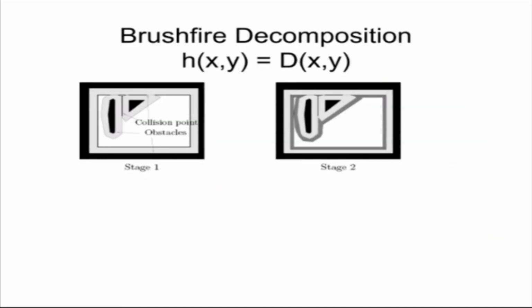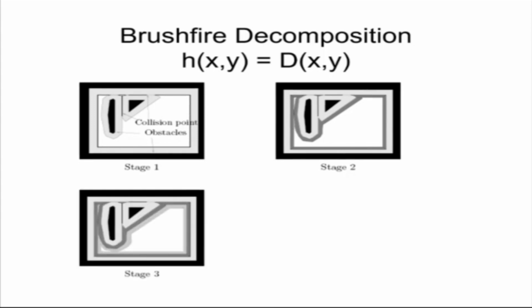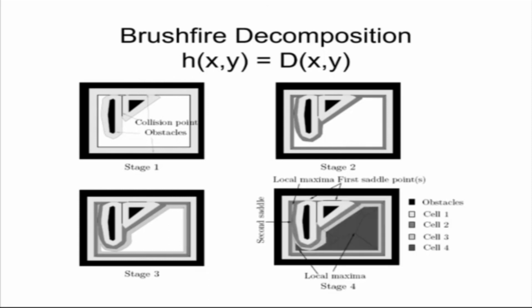Now from here what we can see is that we have divided the full space into a number of points. And so this is my first point, second stage, third stage, and fourth stage. So how many cells are there? So we can see that these are 1, 2, 3, and 4 cells, and the black one is the obstacle cell. So I have basically got, using cell decomposition, 4 cells. Now I can clean each of the cells one at a time. So the coverage algorithm basically starts performing an exhaustive walk on each of the cells one at a time.